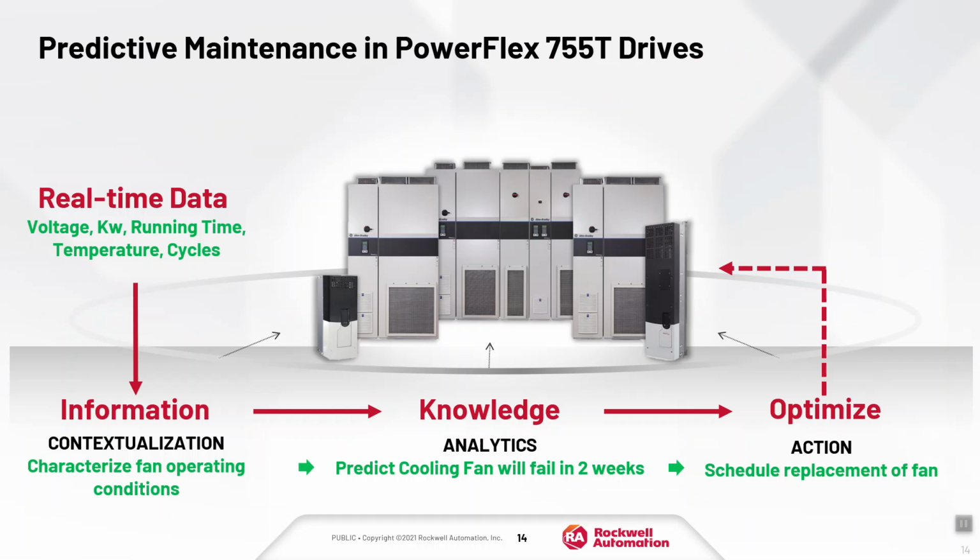So what we're doing in this case is we are monitoring real-time data like voltage, kilowatt hours, total running time, number of cycles, the temperature that the drive is running at, and using that information and contextualizing that in a way to characterize a couple of different conditions.